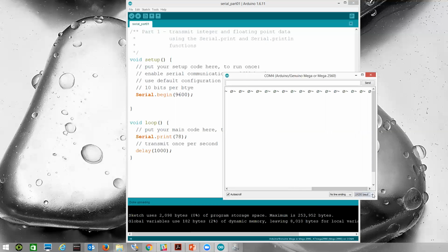And indeed we do, because we're transmitting what we want to be a 7 and an 8 here, but that's not what we're receiving. Similarly, if I change that to some other baud rate there, we get a different set of characters. This is now sampling 4 times faster than this is transmitting. So you can see at these different baud rates, now I'm not getting anything. It just doesn't even have a printable character.